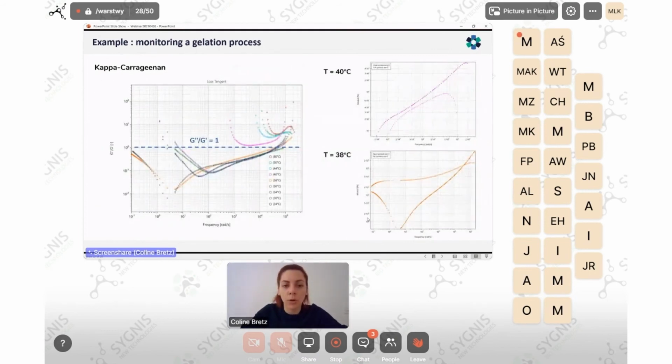We can see this more closely by looking at pure rheological quantities. People would typically look at the G prime and G double prime, which we show here between 4 degrees and 38 degrees, where you can really appreciate the difference in behavior observed. So we go from a state where we almost have a gel. We see that the loss tangent here is very, very close to 1.